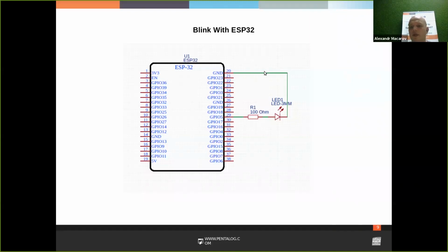You can use any other pin number if you're connecting an external LED. If you're using the internal LED, from what I have seen, it's mostly located on pin 22 for this microcontroller, but there may be other variants where it's situated on some other pin.